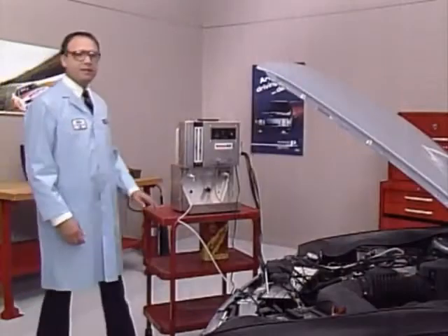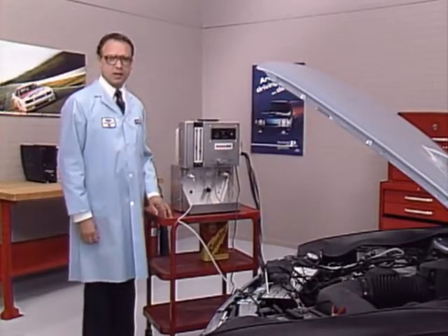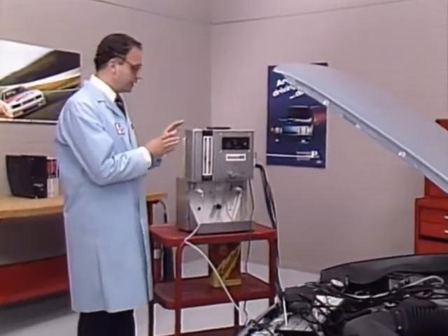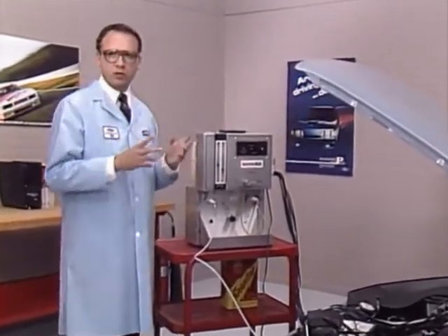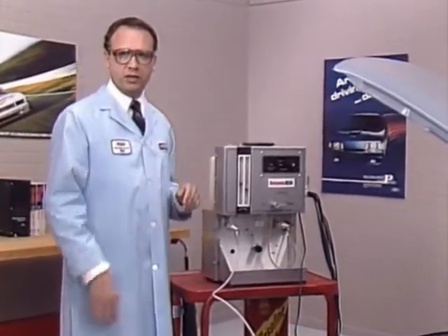However, if the float is not in the correct range for any one of the injectors, clean the injectors. You may repeat the test up to a maximum of 3 times to confirm the results. When you've finished using the tester cleaner, shut off the engine, then disconnect the tester cleaner in the reverse order of hookup. But we'll leave this tester connected so that we can clean the injectors.